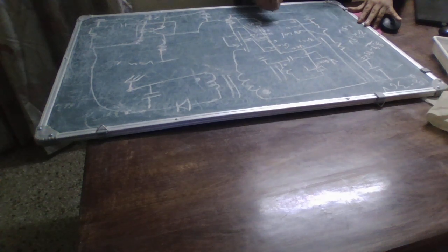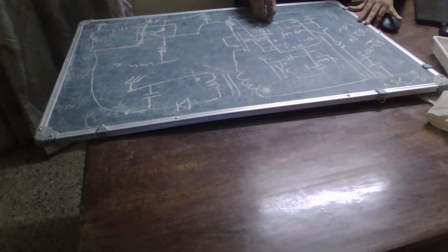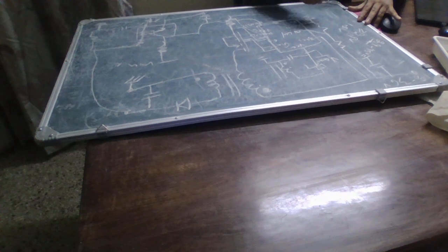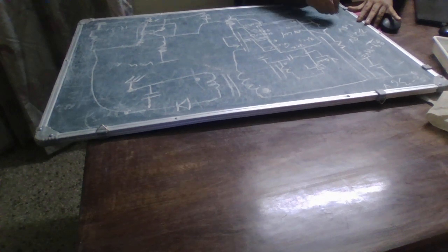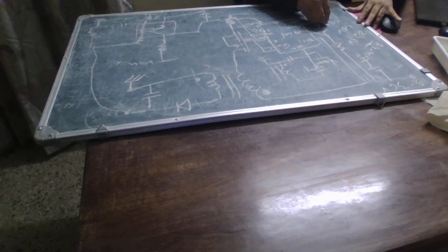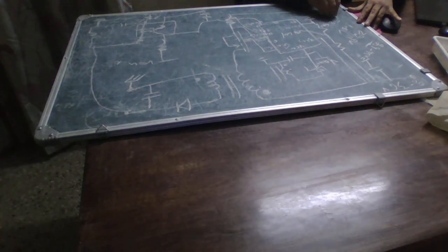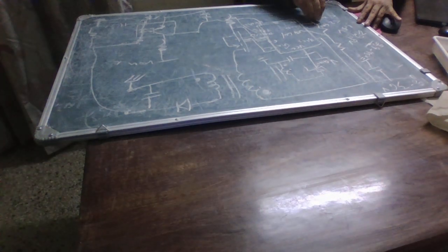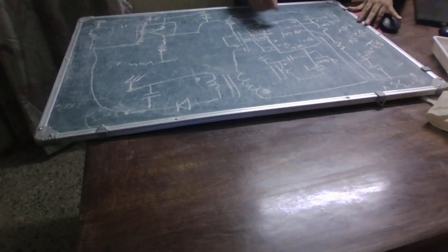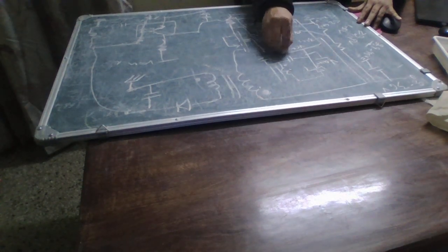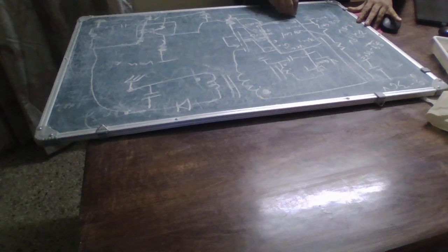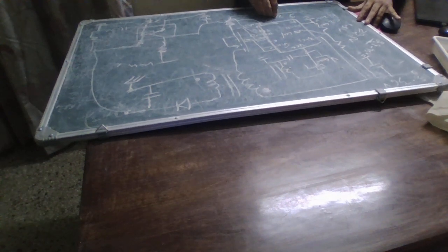The input transient protection is given up to 50 volts. To minimize battery drain, the shutdown current is less than 2.6 microamperes, and the operating current is less than 700 microamperes. The switching frequency this IC can hold is 2.2 megahertz.